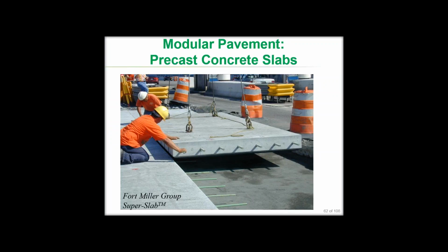If repair and rehabilitation is an objective, and short closure windows are a must because of the traffic volume, then one type of modular pavement would be a precast concrete slab, as shown here. These can obviously perform very well, and these aren't necessarily considered a short-term fix at all.